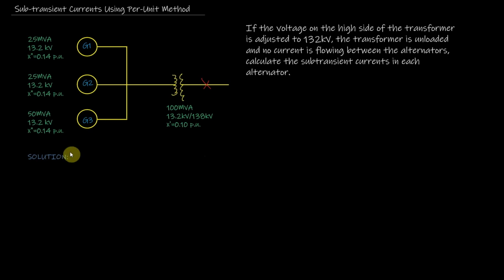Okay? So for this example, ang gagamitin nating base power is S base is equal to, let's say, 50 MVA. And then ang voltage base is equal to 13.2 kV. So gamitin natin itong parameters or itong mga values para sa generator 3 as base values.